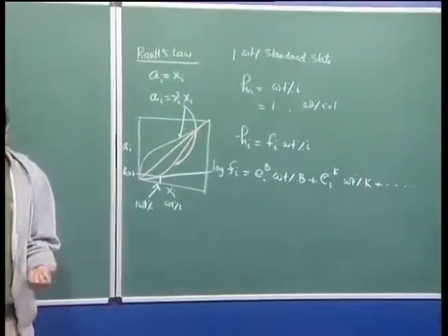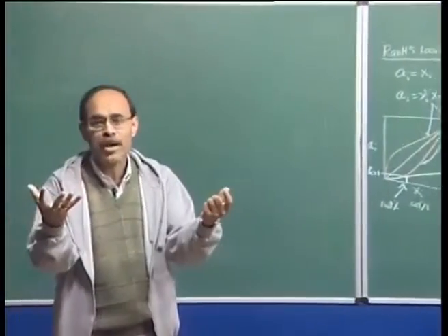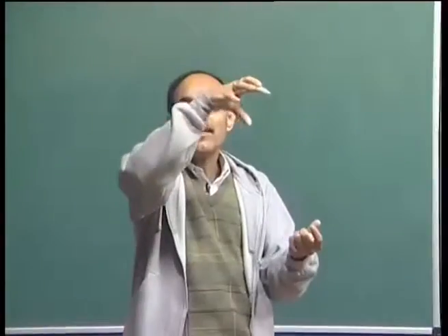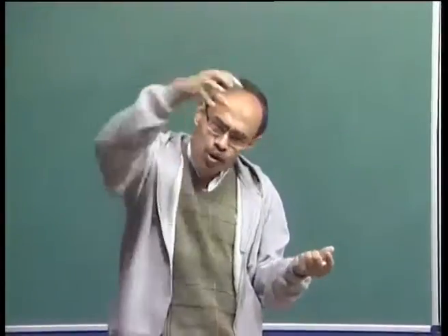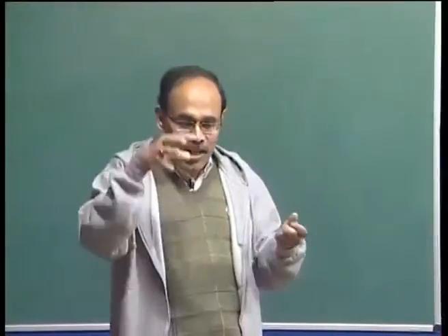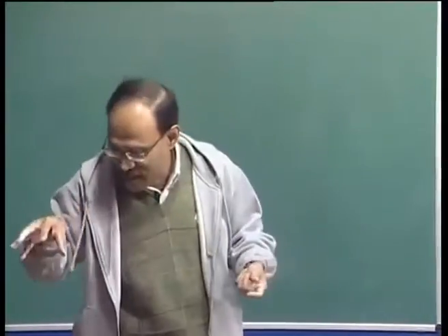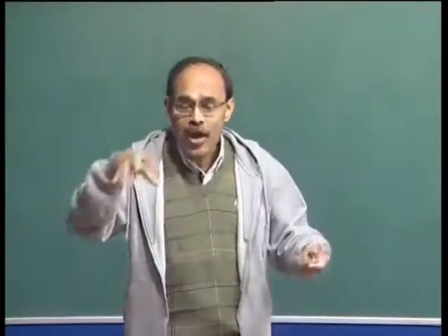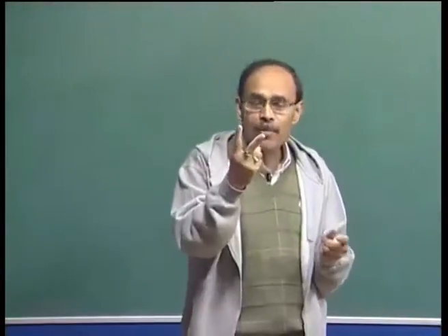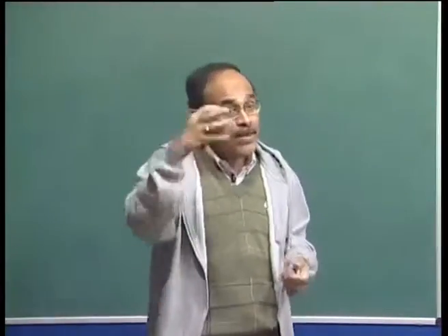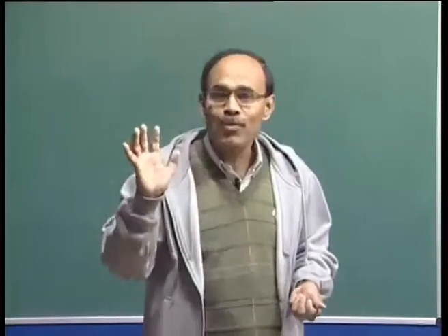Now, you must understand that when I have iron and sulfur, for example, I can measure the activity of sulfur. Now, when I introduce carbon into it, it becomes a 3-body problem. So, there is carbon-sulfur interaction, carbon-iron interaction, and sulfur-iron interaction. As a result, in a 2-component system, iron and sulfur, whatever activity I measure, in the presence of carbon the same activity will not be measured.